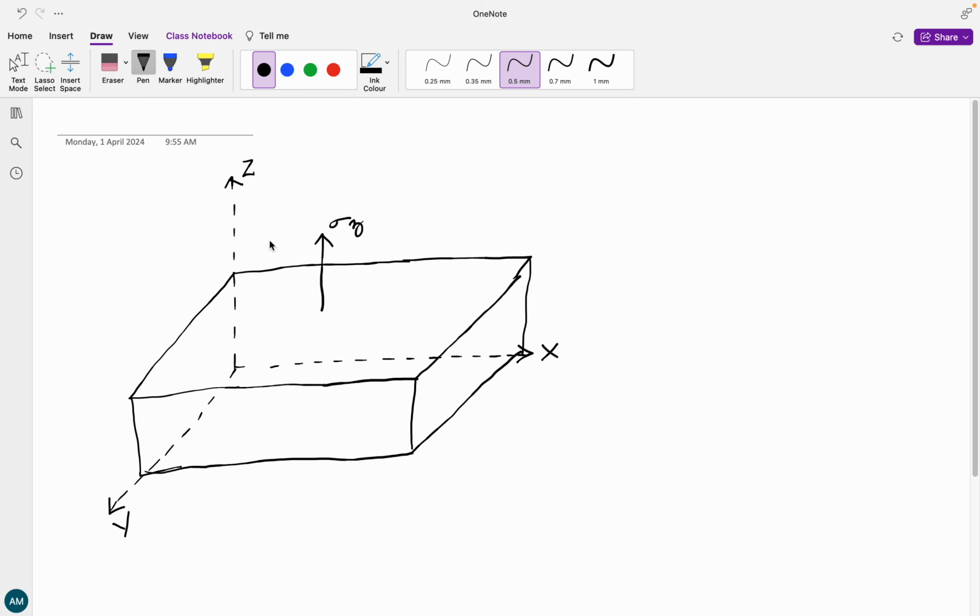You can see that the normal stress is parallel with respect to the z axis, and then the shear stress, which is parallel to the x-axis, and another shear stress which is parallel to your y-axis. Now the shear stress is going to be tau. With respect to the z-axis we write z, and it is parallel to x, so tau zx, then tau zy parallel to y. These are the forces that are going to be acting on the top surface of our parallelepiped.